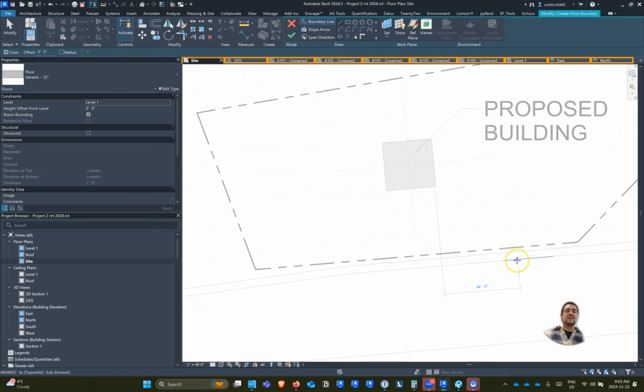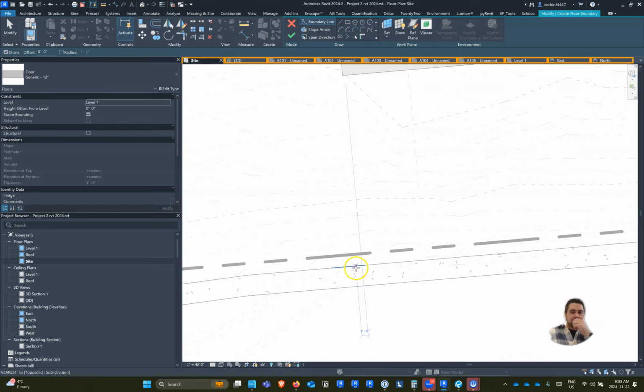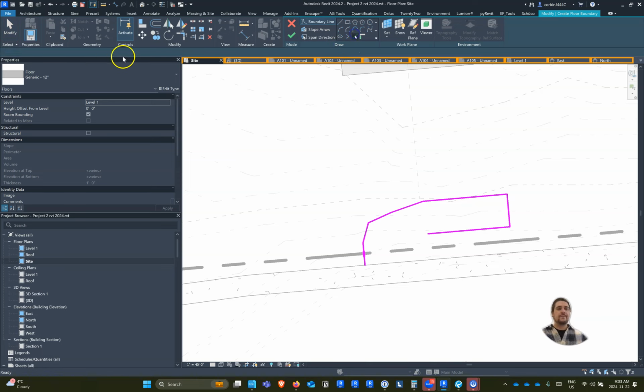So if you've been to site, you might find that maybe part of this area is a little bit flatter. But essentially what I'm going to do is I might do something like this. We're going to create a straight kind of connection and do something like that. And we'll come over to here, kind of flatten out. And because this is a bicycle pathway, I'm going to maybe make it a little bit wider. So let's make it 8 feet. And we're going to do an offset of 8 here. I'm just going to offset these lines a little bit.